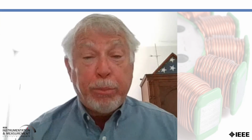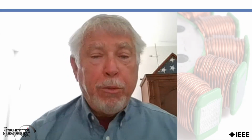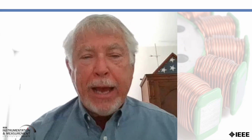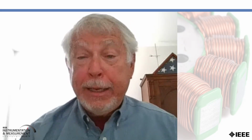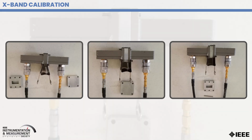Once a calibration is performed, we can make a measurement on a sample. The sample shown here is a piece of waveguide machined such that it will fit into the quarter wavelength waveguide section. This illustrates the calibration. Going from left to right, we have a measurement of the through, a measurement of the quarter wavelength line section, and finally the measurement of the reflect standard.